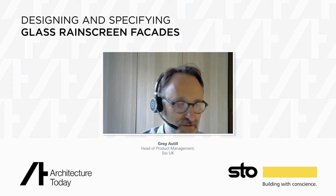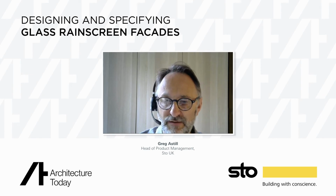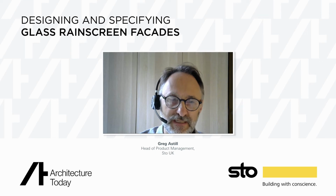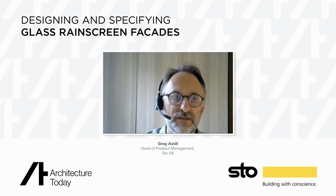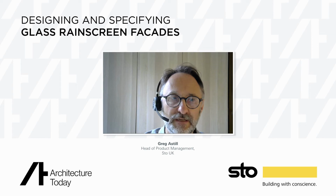What's particularly good to note about Sto Ventec Glass A2 is that we did this test on the front face, but also on the rear face as well, which is the face into the cavity. That's also possibly where a fire is going to propagate, as you will typically get a chimney effect in a ventilated rain screen. So it's quite important that in that cavity you have as little flammable material as possible. We're pretty safe and secure that the panel itself is not going to ignite in any way, whether the fire's on the outside or the inside of the cavity.